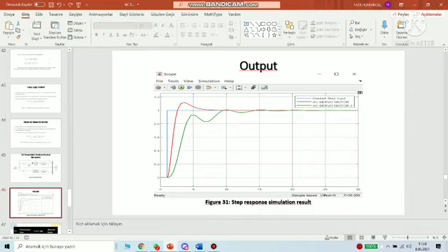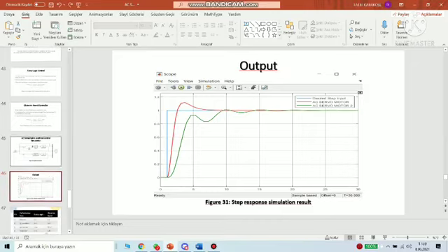There are three lines here. What are these lines? What do they mean? The red line is fuzzy logic control of the AC servo motor position control. The green line shows us the approximate position of the AC servo motor with observer-based control. And the blue one is the desired step response of our simulation. We will compare these two control systems with each other.